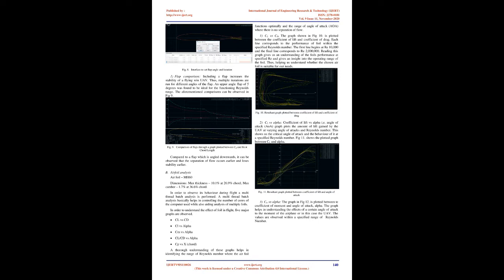The initial step is to confirm the dimensions of the root chord of said UAV. In the case of a flying wing UAV, the length of the root chord primarily depends upon the components that are to be installed within the body of the UAV. These components include, but are not limited to, the battery, ESC, wiring, Pixhawk, extra weights and payload.